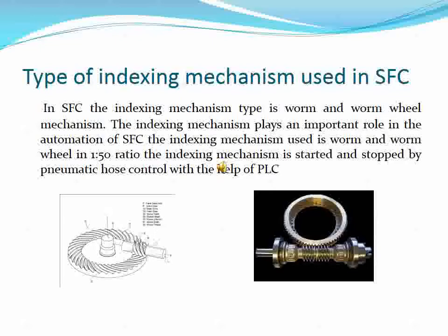Need of improvement in the present method. In the present method, skilled laborers are used to machine the jobs. This makes the labor cost high, and for complex shapes the angle of cut is difficult. The indexing error in the present method may lead to the workpiece becoming scrap, and the table vibration is also high. This may lead to irregular machining of the workpiece. The time of indexing from one tooth to another may vary since it is done manually. This may increase the time of the job.